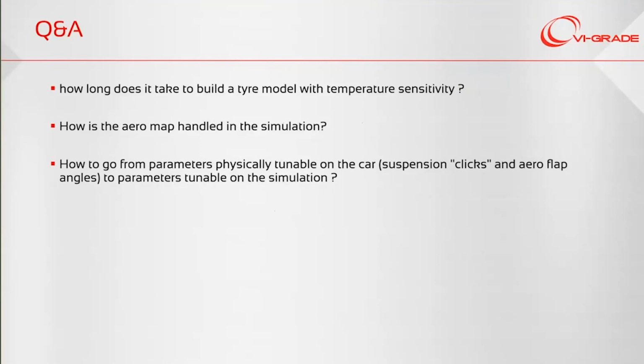In general we can have either a basic aerodynamic model where the downforces are expressed as a dynamic function of the ride height, but we also support an advanced aerodynamic model in which those dependencies can be complemented with additional maps. For example, the influence of pitch, yaw angle, and roll angle can also be included in the computation.